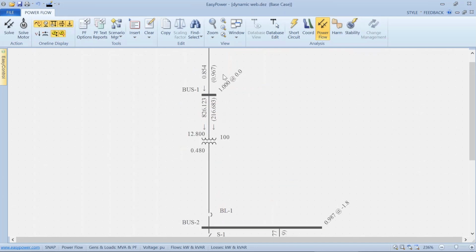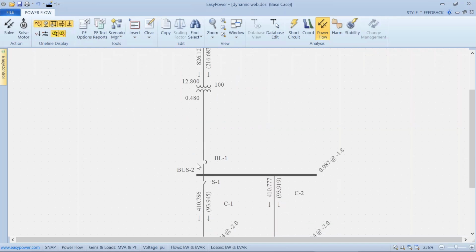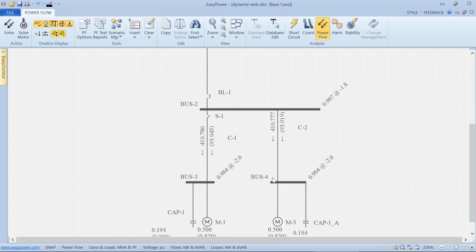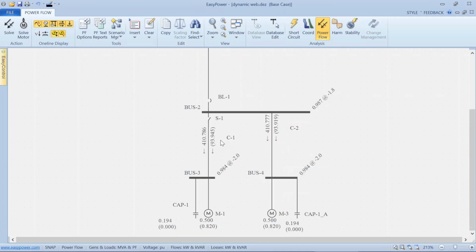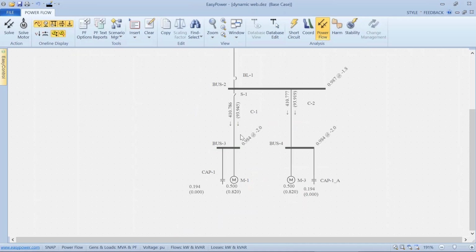We're in the favorable range of 0.96, 0.97, but that's a function of the fact that we have power factor correction capacitors on these large motors. So the question is, what happens when these motors lift off or start off?